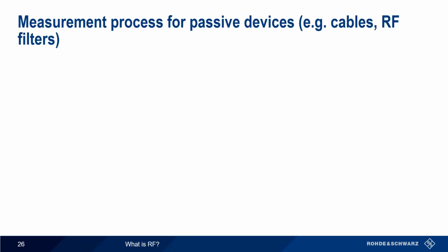The VNA measurement process begins with setting the appropriate values of the key controls to configure the necessary measurements for the DUT. We mentioned in an earlier slide that this involves setting the stimulus type and range, power levels, number of measurement points, and IF bandwidth.